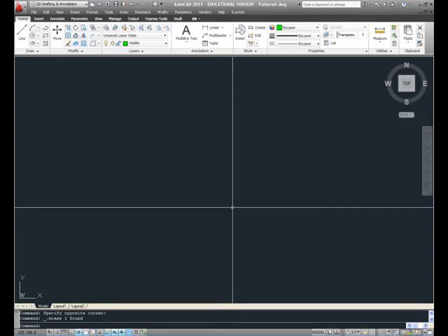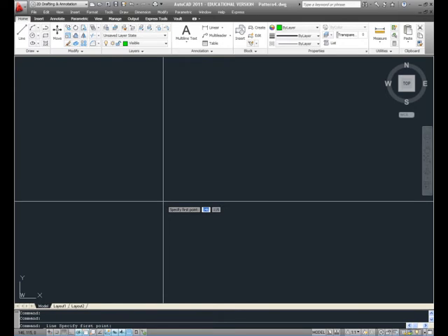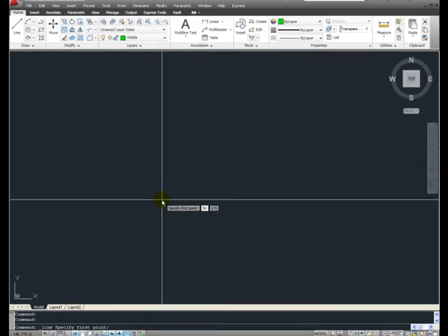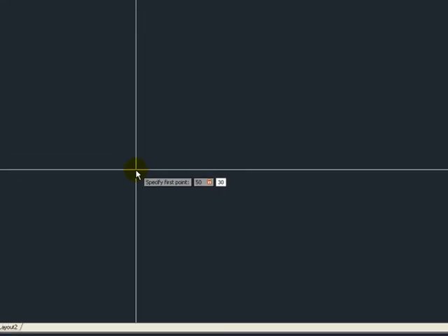Let's start drawing pattern 4 by selecting the line command. The instructions call for us to begin that line at a very specific coordinate of 50, 30. So I'll type at the keyboard 50, 30. It means that this line will begin at a location 50 units in the positive x direction and 30 units in the positive y direction as measured from the origin of the drawing.